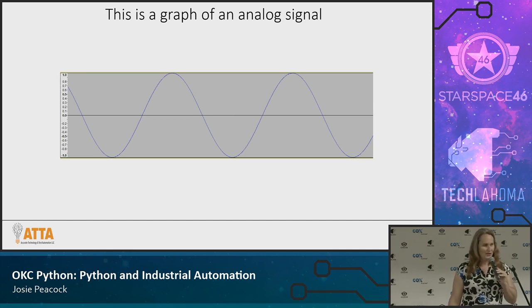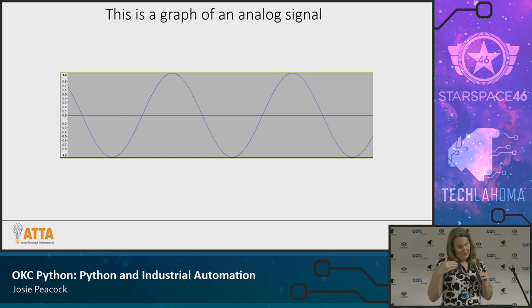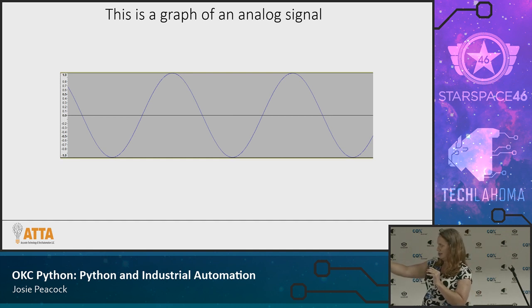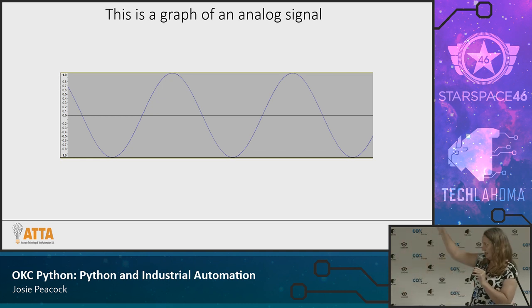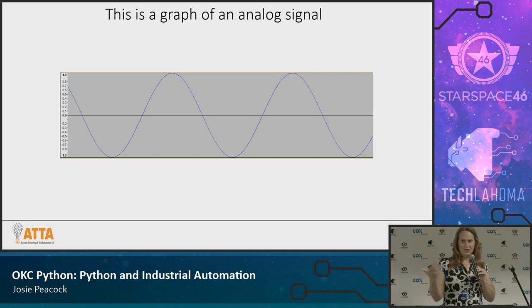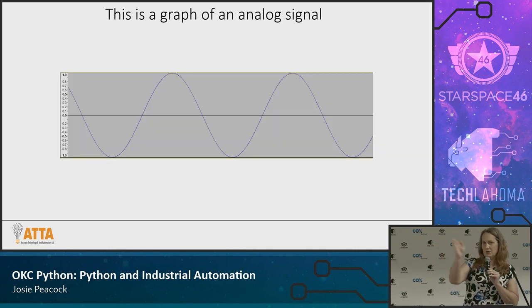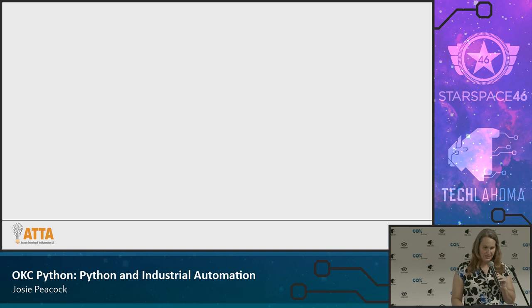So everybody's an expert on analog to digital conversion now, right? But you are actually going to need to know this, especially if you're doing digital signal processing, because you can go through a fast Fourier transform, and you're going to change that x-axis to, instead of time, be frequency. So you're just going to see one peak at 60 hertz, which is just going to be a line. Like I said before, you'll have the crazy signal with the noise, and it's going to be able to break out each one of those and the amplitudes, and you'll have that information saved.